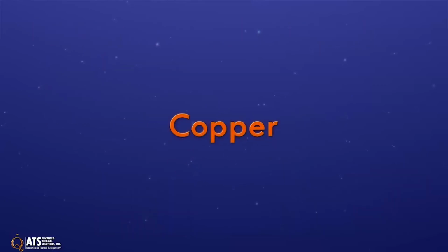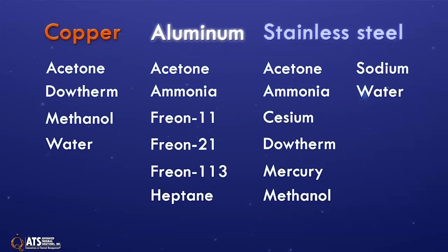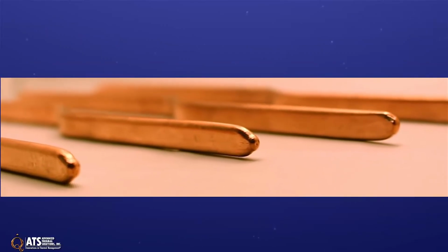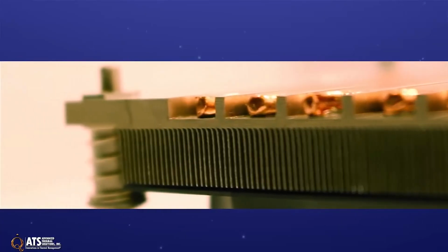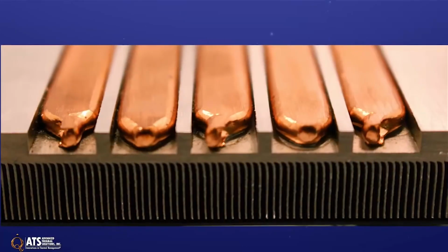Material types include copper, aluminum, and stainless steel. This list shows some of the compatible material and working fluid combinations. ATS's flat and round heat pipes are made of copper to cover the broadest temperature range with a cost-effective solution. ATS can design with other metals and advise customers on application-specific solutions with careful consideration for the cost-benefit trade-offs, the materials, and working fluids.